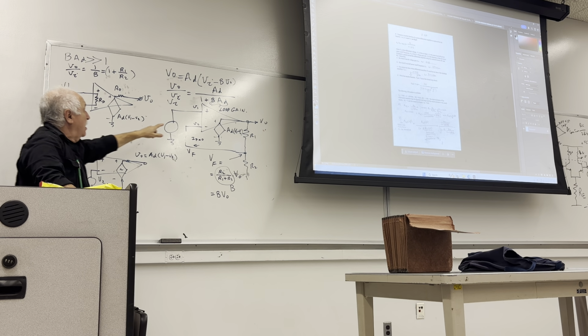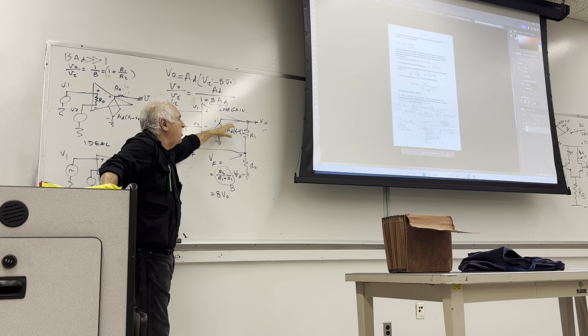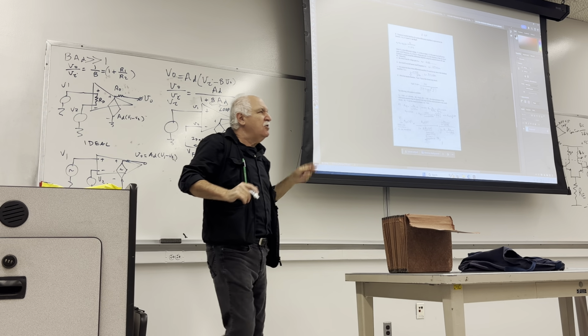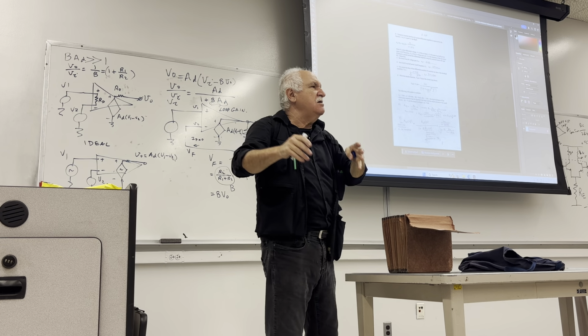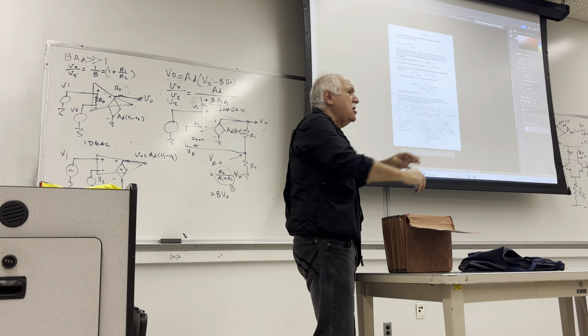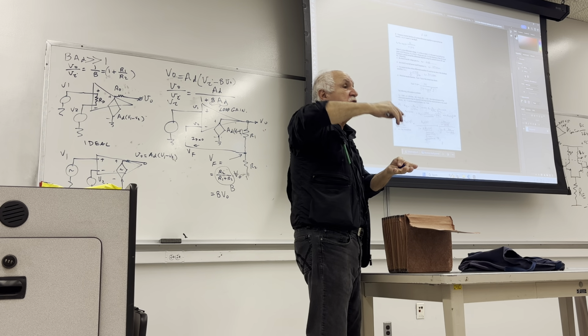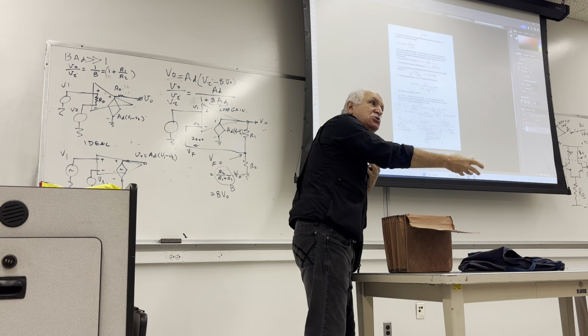So, when you're designing an amplifier, you're building an amplifier, you have all those internal stages. You are facing beta here, beta there, beta of this transistor, GM of the other transistor. Temperature changes VT, thermal. VT changes, GM changes, gains change, okay?